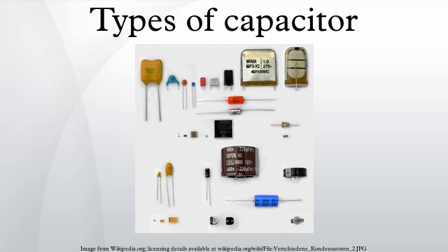For film and ceramic capacitors, normally specified with a loss factor tan δ, the ripple current limit is determined by a temperature rise in the body of approximately 10 degrees Celsius. Exceeding this limit may destroy the internal structure and cause shorts.